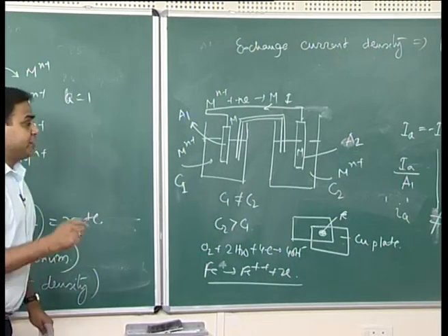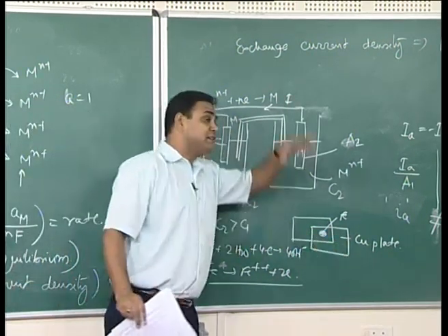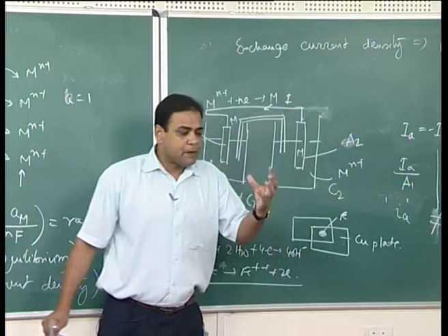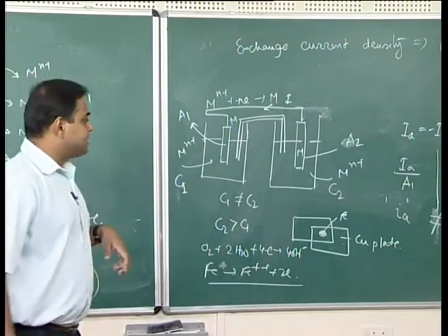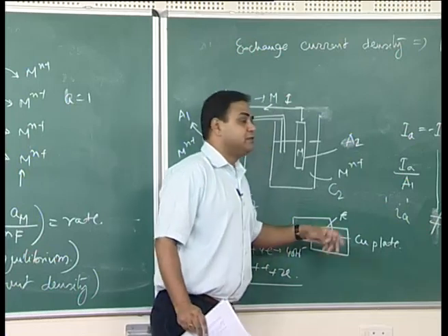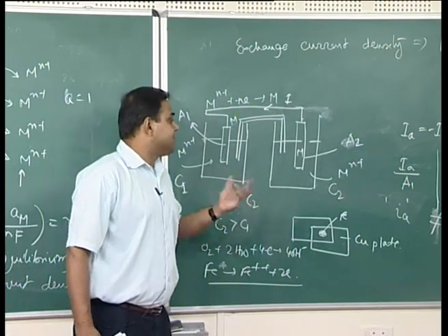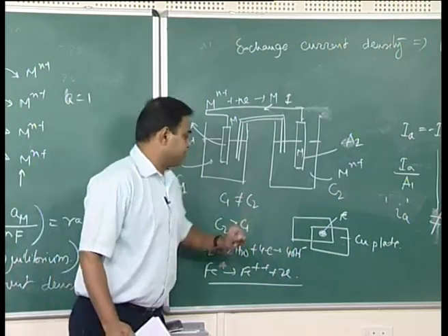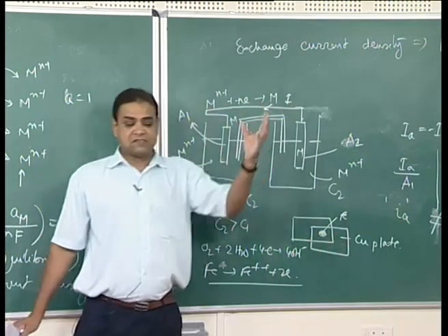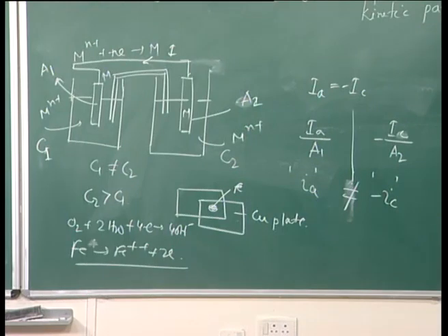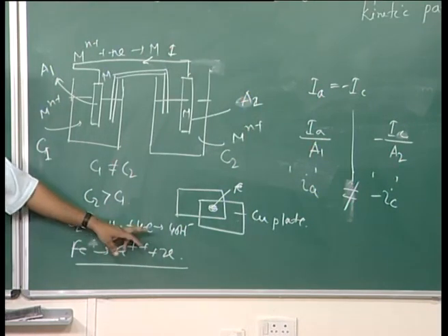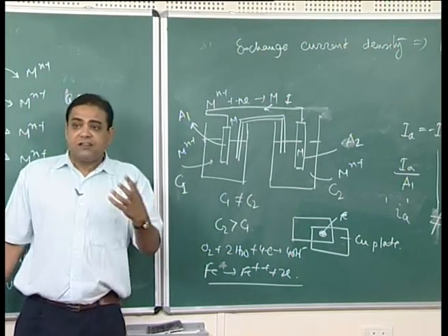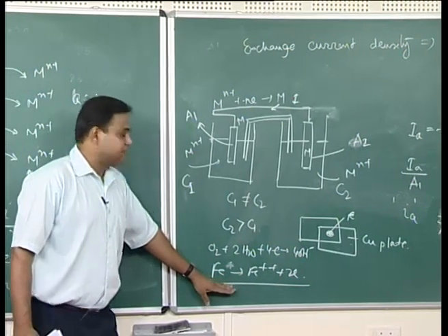This reaction is taking place on the iron surface, and if you compare the galvanic series, which I will come to later, you will see that when copper and iron are coupled galvanically, copper acts as the cathode and iron acts as the anode, so the anodic reaction takes place on the iron surface. Now, here two things. One, you have a huge surface area for the cathodic reaction, so you need a huge amount of electrons. Where will these electrons come from? They will come from the anodic reaction.